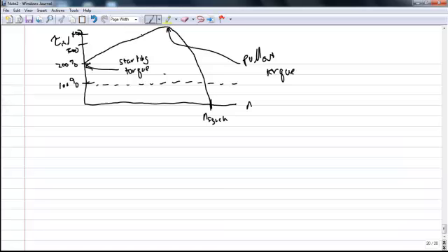The starting torque is larger than the full load torque. This is important because that means that carrying any load up to the rated load, we can start the motor simply by applying the power. We don't need any special starting circuitry, generally speaking, with induction motors.